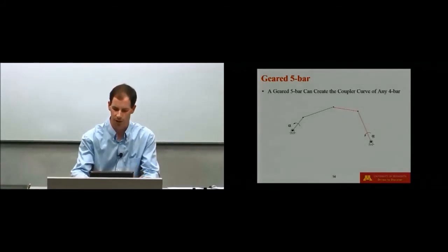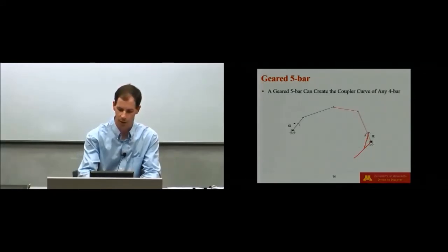So what I'll sketch is maybe something coming off like this, and these two are rigidly connected. And then I'll create this one, hopefully parallel, same length, and so that blue link and that link are rigidly connected. And then I will have these two moving pivots right here, and I will connect them with a link. And so I formed a parallelogram linkage.